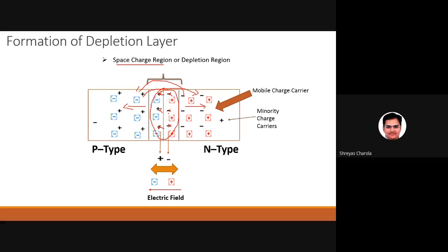So in the depletion region, we have high resistance. Such resistance cannot be broken by an electron in the n type to move towards the p type material. And that's why another name we call it is the barrier potential. Barrier is nothing but a kind of wall that has been generated. Or we call it a built-in potential, because the potential has been generated by itself. That's why we call it a built-in potential. Clear, all of you?